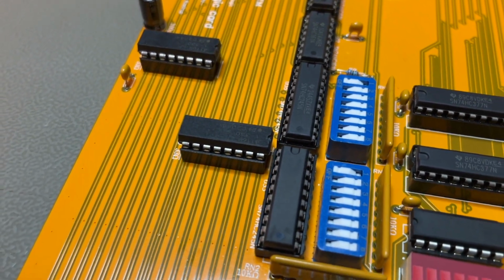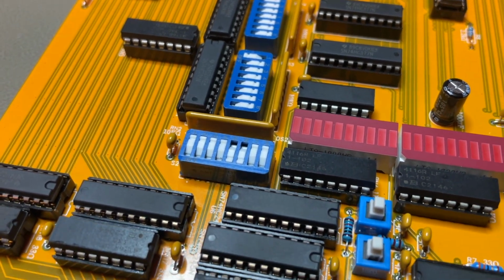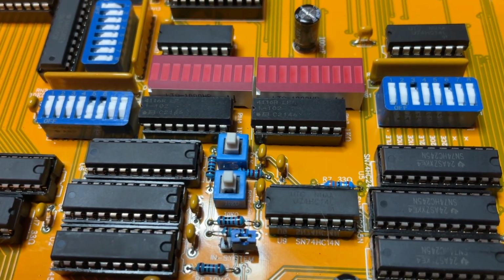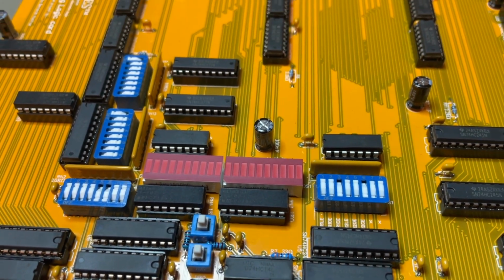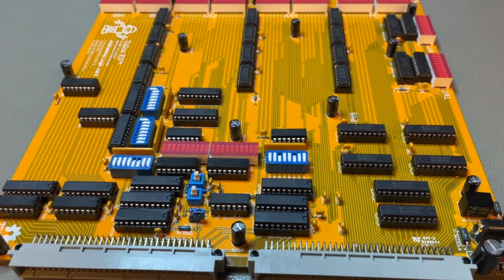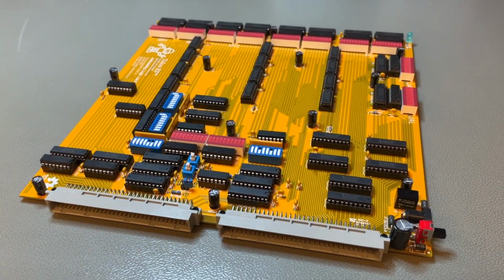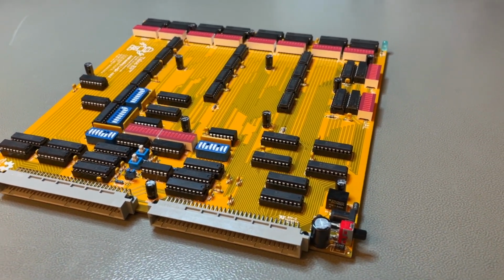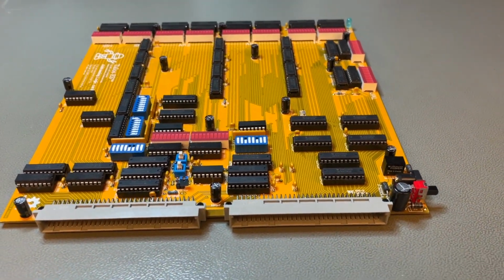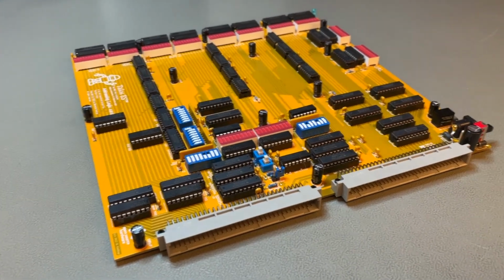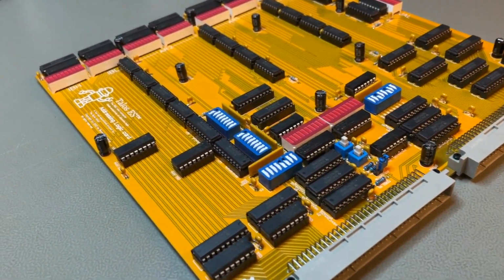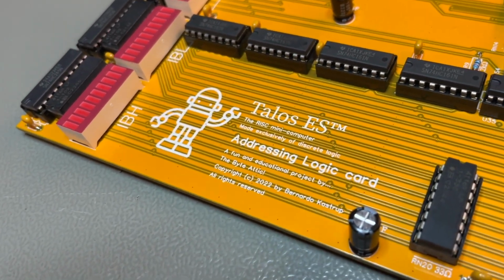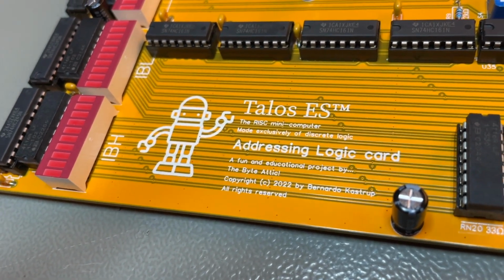When possible, I put some copper fill in between critical lines, and then I stitched it carefully, making sure that the metal in between never floats. You can see that area in the center where the control signals come in, and the push buttons, backplane connectors. I'm quite happy with this board, even though it was the most difficult to design of all 3 so far because of the sheer amount of signals. And finally, zooming in on the silkscreen markings identifying the board. So let's go ahead and test it now.